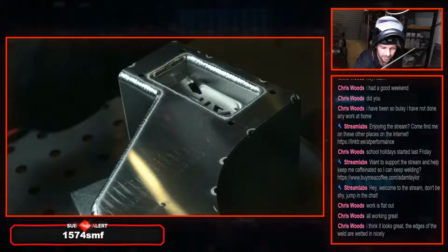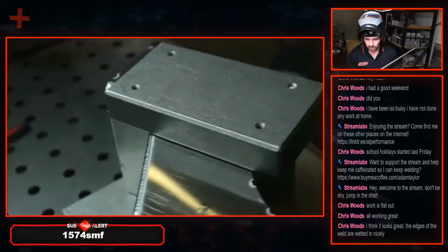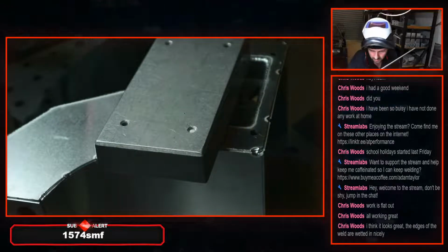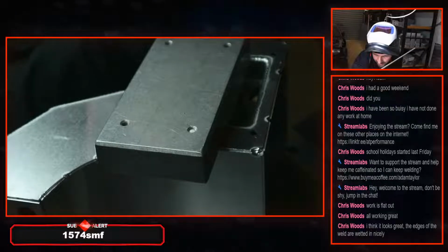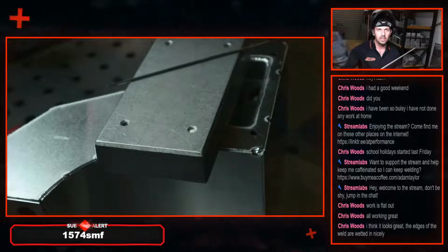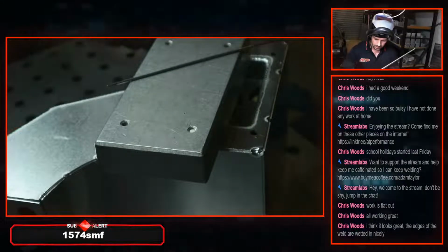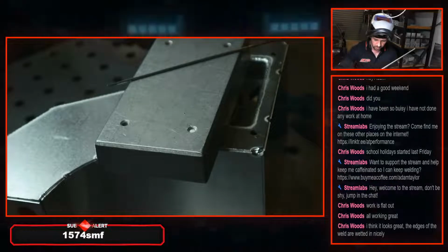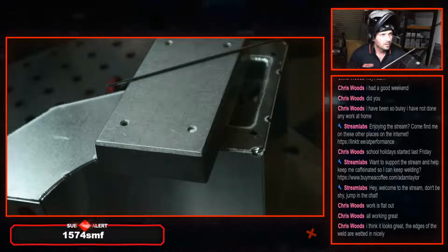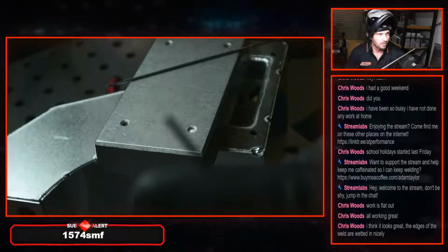Might swap this chill block out, grab the big one, and get across these fronts, and I'm also going to swap that tungsten out. So we did just pop in a lanthanated tungsten, and I don't know if you can see it in the welding camera at all, but it's balled itself, but it's also formed nodules, which there is no chance I'm going to get this camera to show you that.